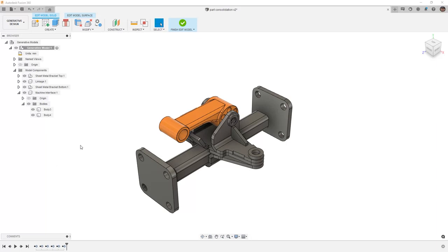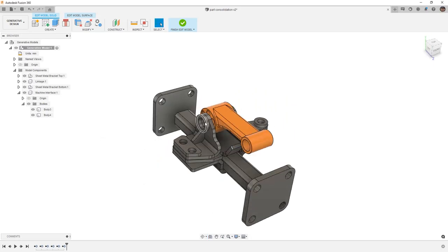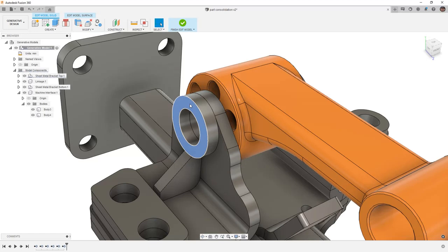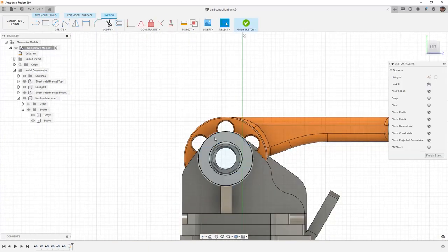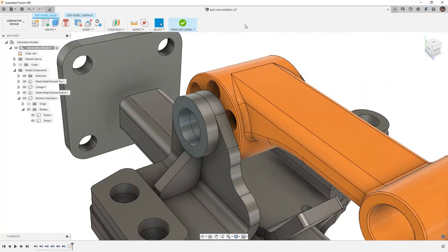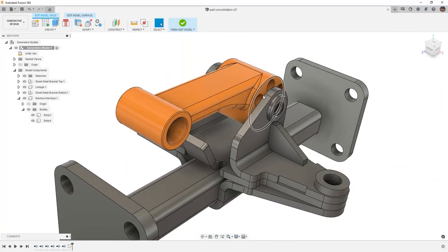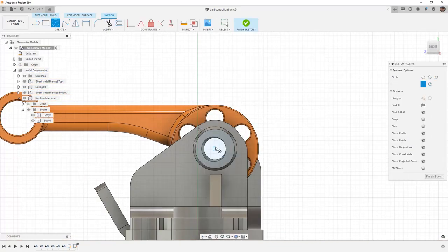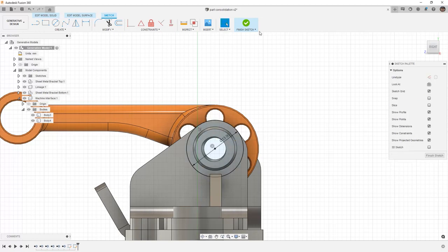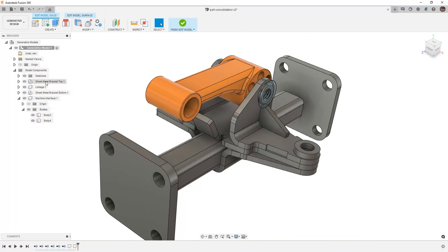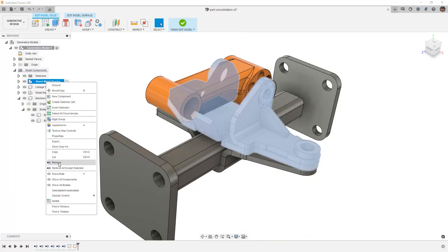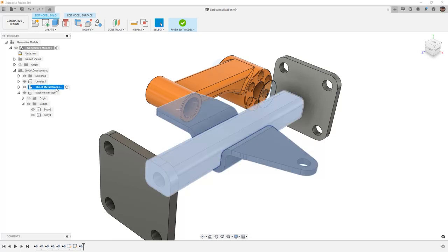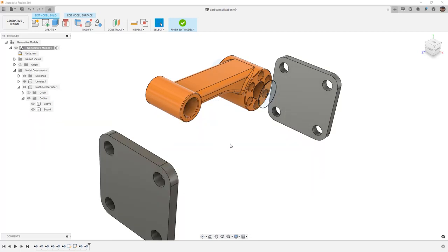So what I'd like to do is first make sure that we capture some of this data. I'm going to begin by creating a sketch, and I'm going to use this exact geometry. We're going to finish the sketch, and then on the other side, I want to do the same thing. I'm going to create a sketch on this face, but I'm going to use my circle tool with C on the keyboard, and I'm going to create a larger diameter circle. In this case, we're going to set it to 13 millimeters for right now, and we'll finish the sketch. Now I can go into my sheet metal bracket top, right-click and remove, and those sketches will be left behind. Then the sheet metal bracket bottom, I can remove that as well.